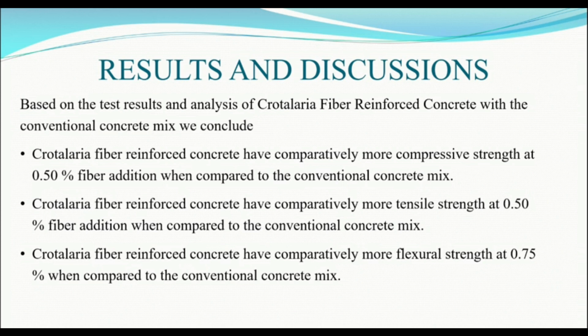And now moving on to the most important part of our presentation, that is results and discussions. Based on the test results and analysis of crotalaria fiber reinforced concrete compared with the conventional concrete mix, we conclude that crotalaria fiber reinforced concrete has comparatively more compressive strength at 0.5% fiber addition when compared to the conventional concrete mix.